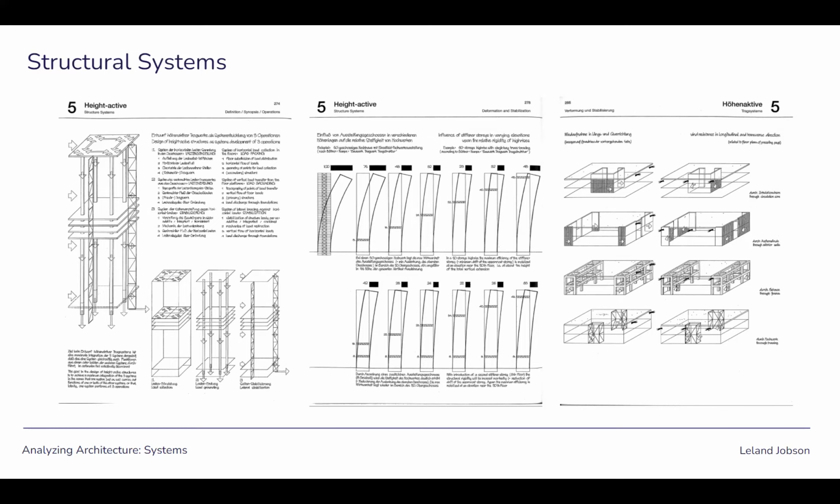When you look at the super tall buildings, because of their slenderness ratio, one of the things that they often employ is either an incredibly strong core at the center that's small, but in a lot of cases, and this is true of the Vignoli building, it's at 432 Park, the structure moves to the outside of the building. So the wall is load bearing on the outside, exterior load bearing wall, exoskeletal structure.